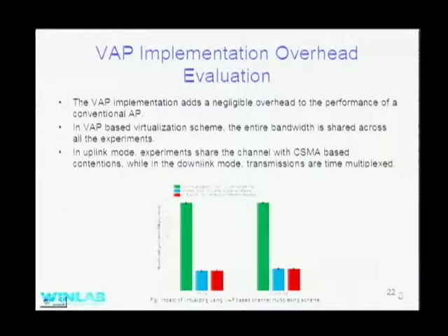But that all assumes all of them have equal signal. Yes, we were checking that the received signal strength, RSSI, at the access point is the same for the 4 clients. Otherwise, for a more robust experimental framework, people might expect to have auto rate or control over those parameters. The moment they start doing any cross-layer stuff or auto rate, then it's not going to work. So I'm pointing this out just for people who might be interested in doing future work on it. Sure.